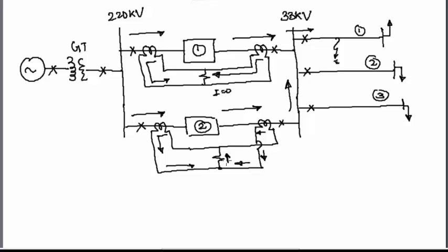This transformer will trip means this relay is going to send a signal to this circuit breaker and this circuit breaker, and both of them are going to operate even when there is no fault within the differential zone of the transformer. Means due to mistake in the circuitry, the transformer is tripping even for through faults. Hence, the connection of CTs should be considered carefully while designing the differential circuit of the transformer. This was all about the basics of differential protection of a transformer.